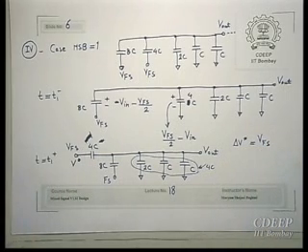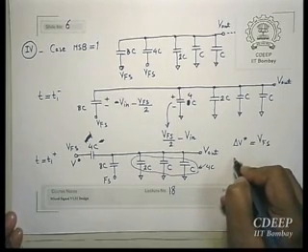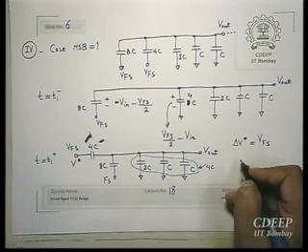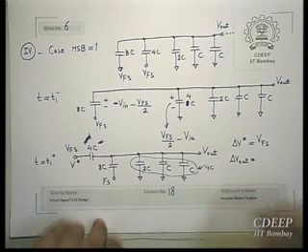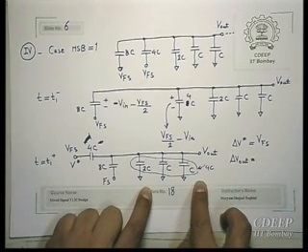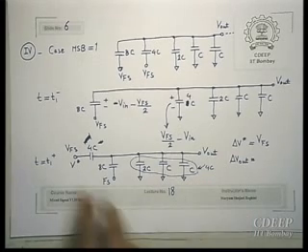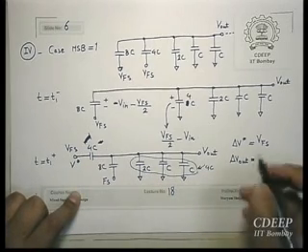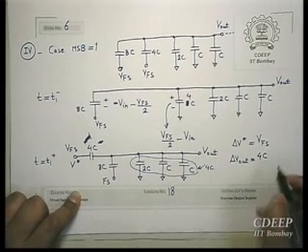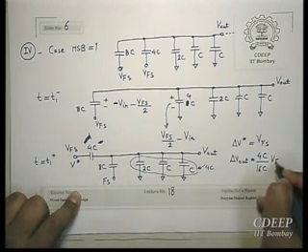So therefore again we will go with that delta V. So delta V out is equal to, so we have 4C divided by the whole value, which is 16C, 4 plus 8, 12 plus 4, 16, again the same thing, and this was V full scale, right?